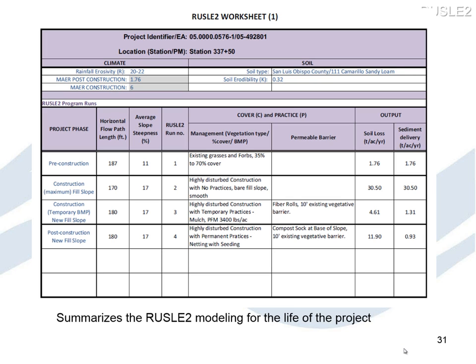But in the section of the permit that deals with final stabilization, this is really the number that matters: demonstrating that the sediment delivery post-construction is equal to or less than what you have pre-construction. So again, in this case, we have a project that could submit for termination and show that it satisfied the final stabilization criteria. So that's it for Russell 2.